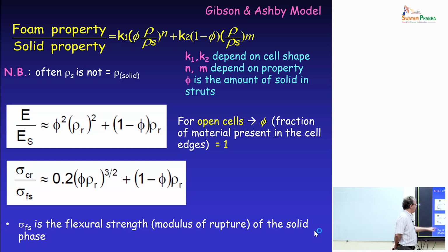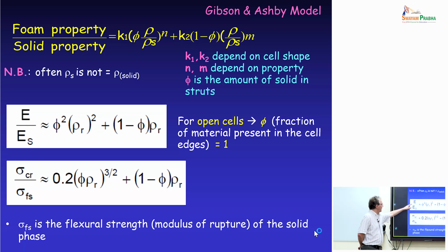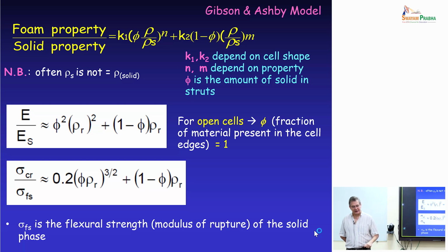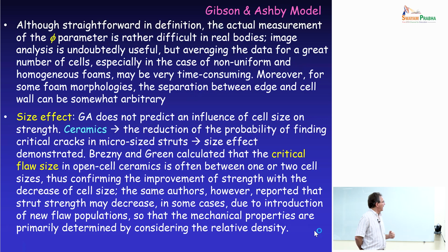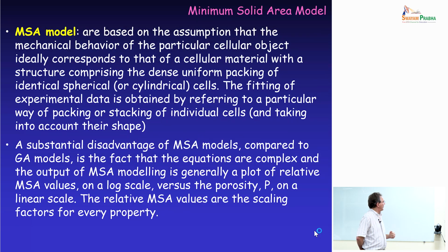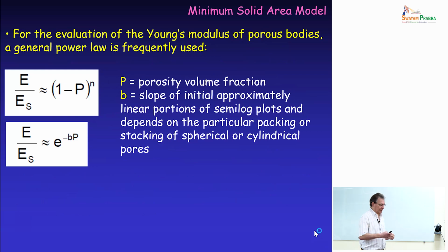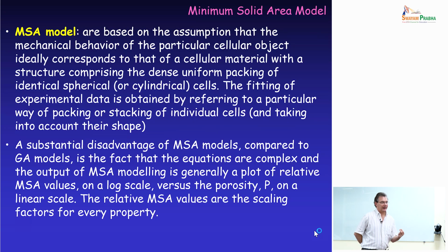There's one important thing to point out: these values are parametrized based on the strength of the material. And for ceramic materials, you have issues in determining the true strength of the material, because what people typically do is simply put into the formulas the bending strength of alumina obtained using a different approach.